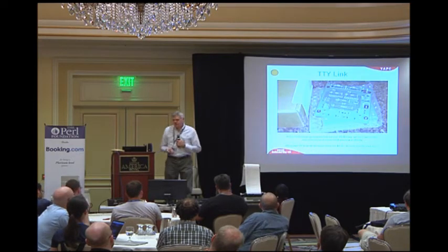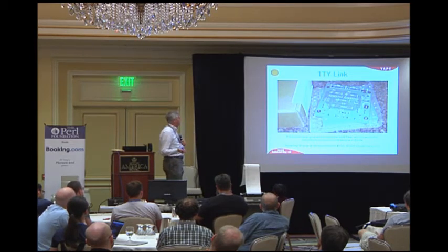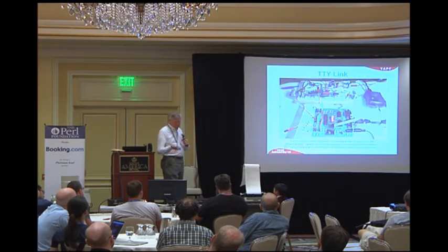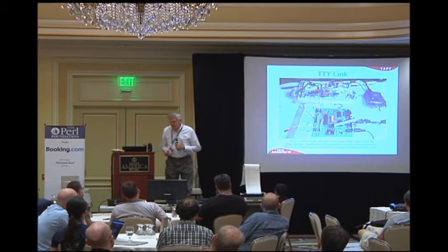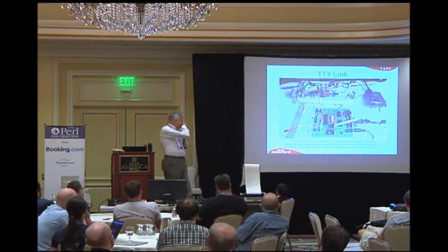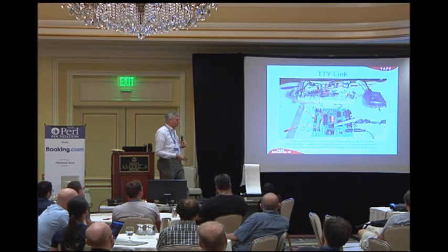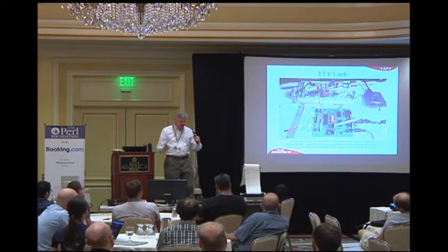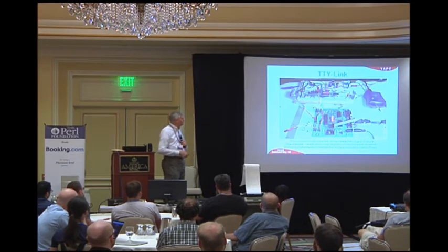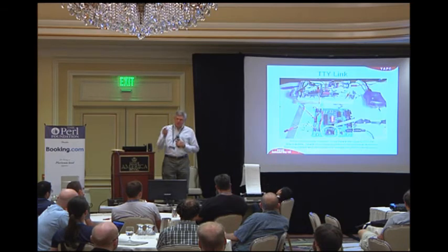So then I sent these off to China for $100. I got 10 boards, and they came back in very good condition. Quality looked great. I put all the chips on, and it didn't work. This was my first project, and I had no clue. You know, okay, try this voltage, and the voltages were a little bit off. But I eventually figured out in about 2 hours that this device right here, my regulator, the leads were backwards. So instead of 1, 2, 3, I had 3, 2, 1.